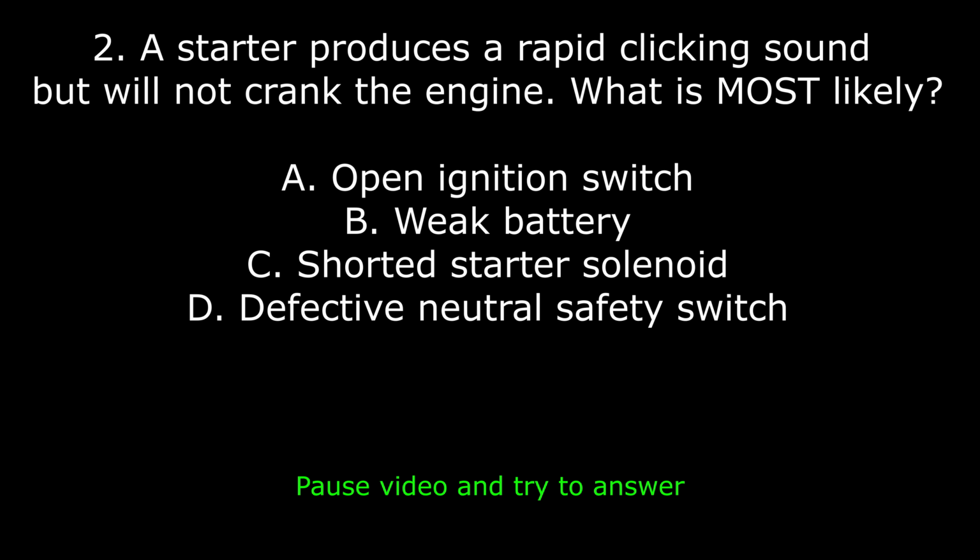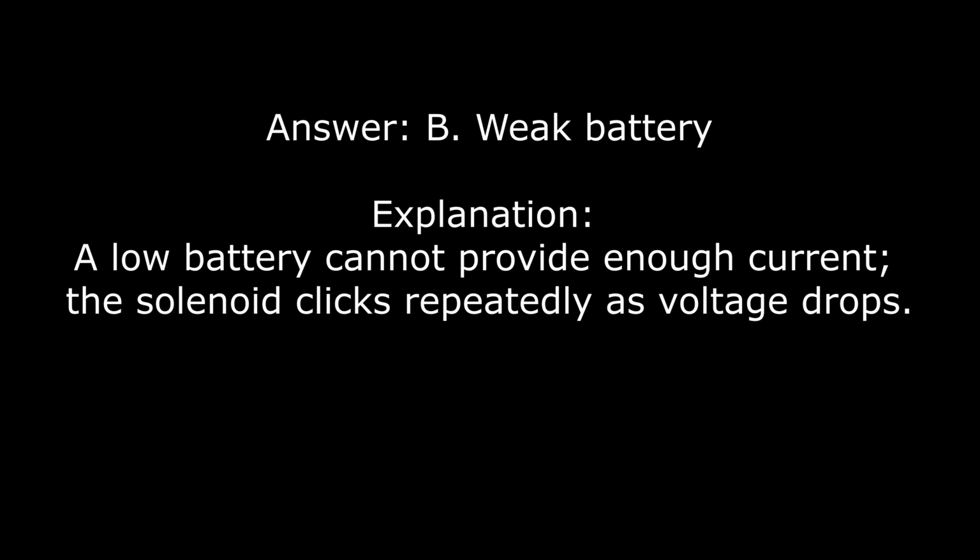2. A starter produces a rapid clicking sound but will not crank the engine. What is most likely? A. Open ignition switch. B. Weak battery. C. Shorted starter solenoid. D. Defective neutral safety switch. Answer: B. Weak battery. Explanation: a low battery cannot provide enough current. The solenoid clicks repeatedly as voltage drops.